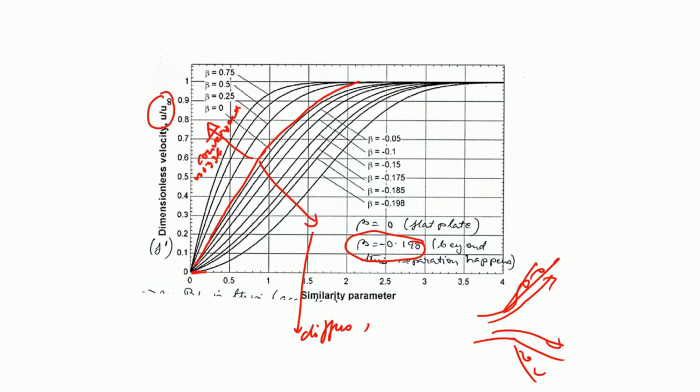So, as you go on increasing the diffuser part, chances of flow separation increase, and as the flow separation increases, you actually have separation of the shear layer. As you have separation of the shear layer, the flow basically separates. On the other side, however, the boundary layer becomes sharper and sharper, as you can see. This is based on the similarity parameter, which is basically your eta, and therefore the shear stress will also become higher and higher.